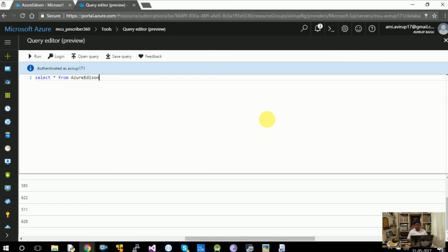So what we have learned through the entire video series is how to hook up the Intel Edison with the Grove base shield and connect an analog sensor to it. From there, we are collecting the sensor data, that is a light intensity value. From the Edison, we are streaming the data through the MQTT protocol to the Azure IoT Hub. And from the Azure IoT Hub, we are using a Stream Analytics job to route the incoming data to a SQL database, and we are ultimately saving the data to the SQL database. So that's how the entire thing is functioning.